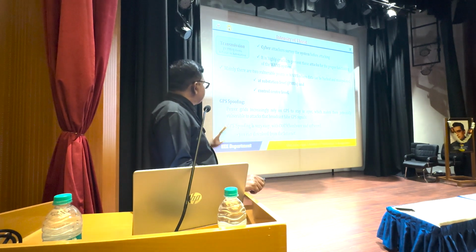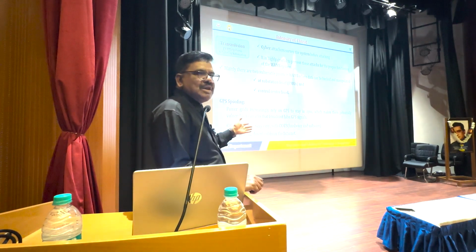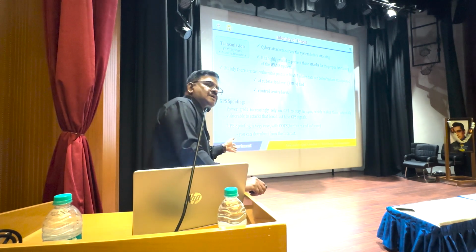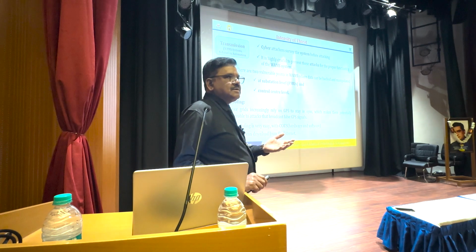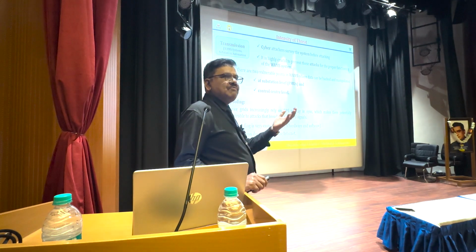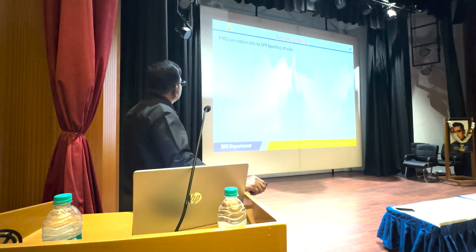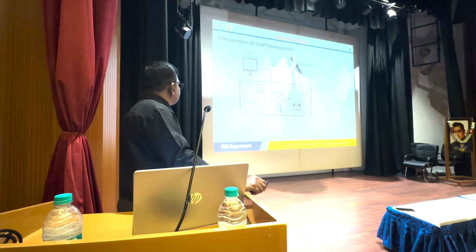GPS spoofing is very easy with COTS software, that is commercial off the shelf. That's what I said: it is available free or at low cost. Everyone is using it, because this COTS software has backdoors or trapdoors, from where it can pass information to those with malicious intentions. You can download it from the internet. So PMUs are vulnerable to GPS spoofing attacks.